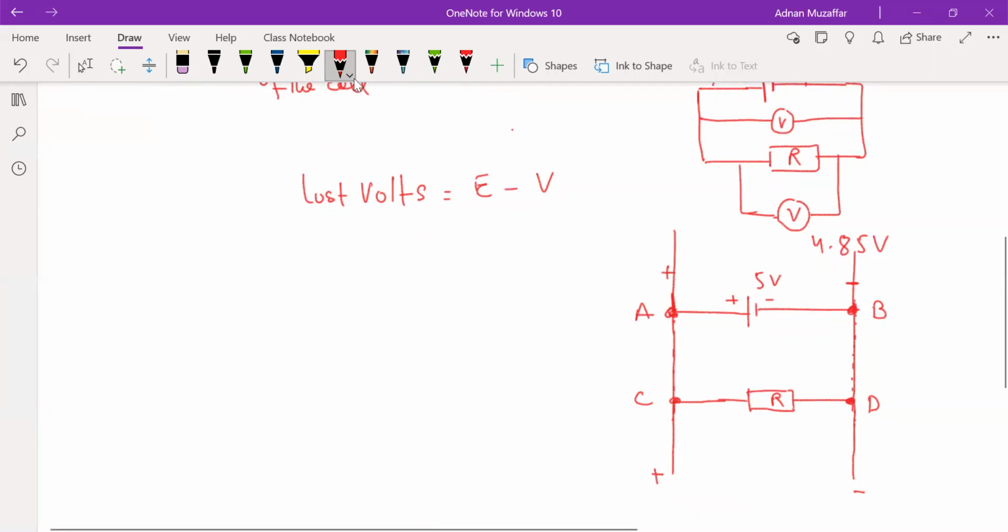So if I want to connect a voltmeter here to measure the PD between these 2 wires, I must use the word terminals. Why terminals? Because this wire is directly connected to the positive terminal of the cell, and this wire is connected to the negative terminal of the cell. So I can call these wires terminals, and I can call this voltmeter reading terminal PD.